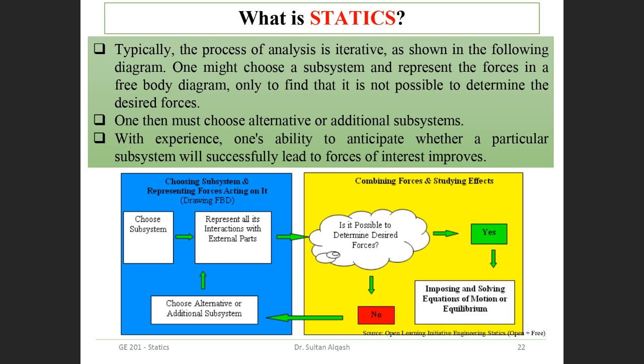Now, the big picture of statics: typically the analysis is an iterative process where we choose the subsystem and represent the forces on the diagram, the free body diagram as we call it, only to find it possible to determine the desired force. And then choose an alternative or additional subsystem. With experience, inshallah, later on after you expose yourself to different problems, you'll find that you have a common sense for finding the forces just by looking at the system.